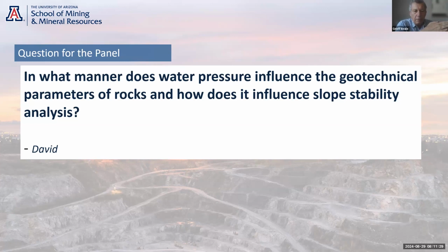The more weight, the more the frictional resistance on that surface, and the greater the shear strength on that surface. So if you put water onto that surface, it provides an upward pressure which counteracts the weight of the material above the surface.